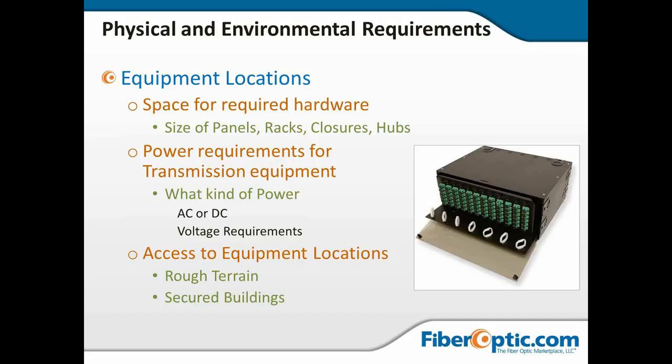What kind of power requirements are we going to need for the transmission equipment? Electricity, are we going to need AC or are we going to run off DC? Are we going to need battery chargers? What are the voltage requirements? I've seen stuff running from 5 volts to negative 48 volts, plus or minus 12 and anywhere in between. So we've got to be aware of our power issues. And then again, access to these equipment locations, rough terrain, secured buildings that we can't get into, and then suddenly we can't maintain the plant in the middle of the night.